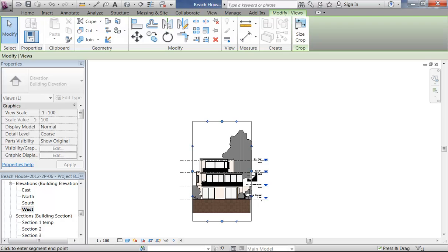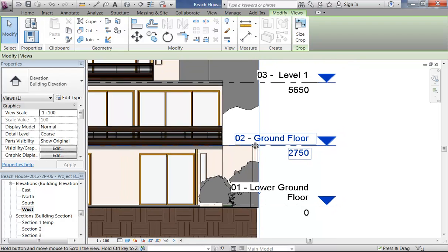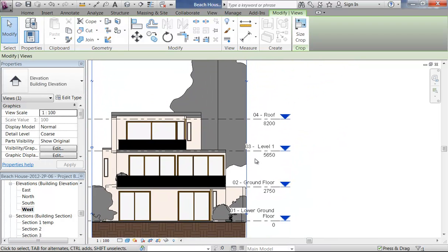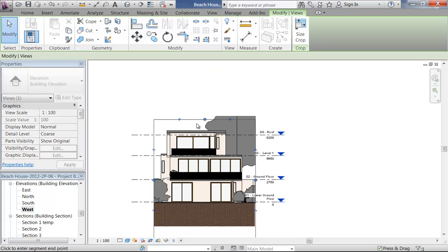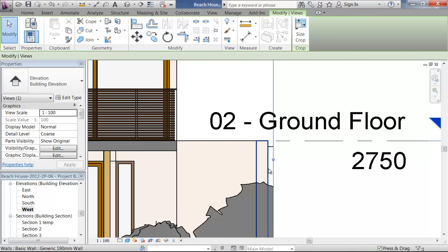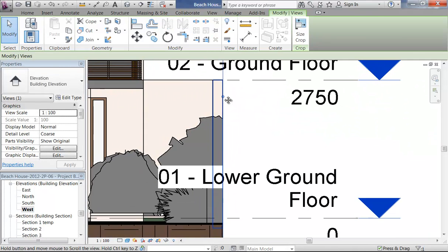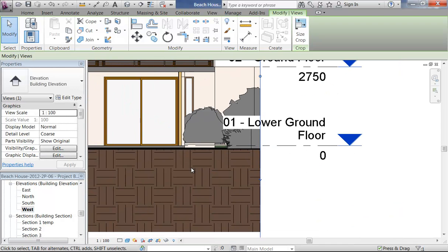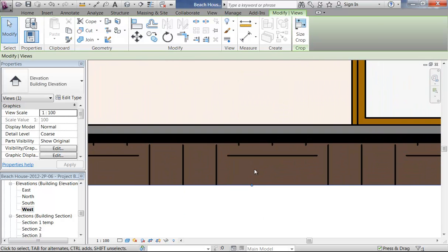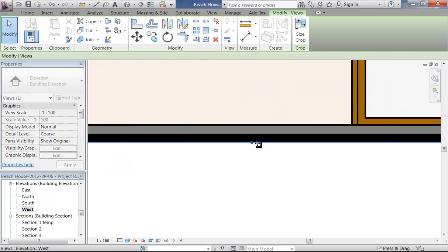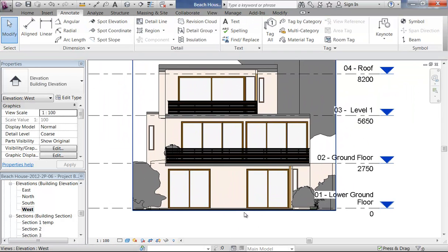So here, you want to get it fairly close to the retaining wall. It's a bit hard to do that at the moment, but once this has been brought down, it's much easier to adjust that side. So there we go, that's all continuous. And now coming up again right to the ground line, just makes it neat. That's how an elevation should look. Only showing the ground hatch when you need to.